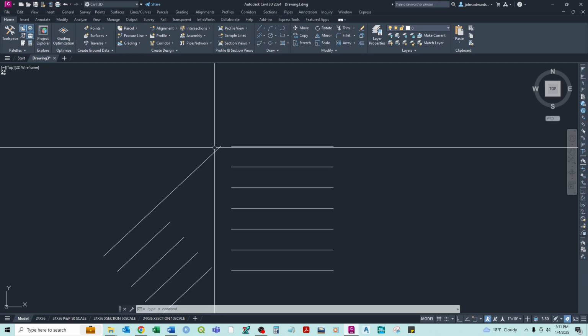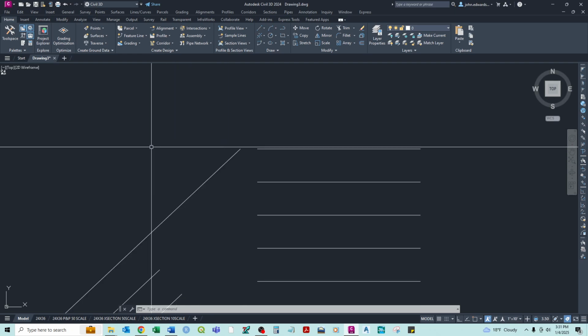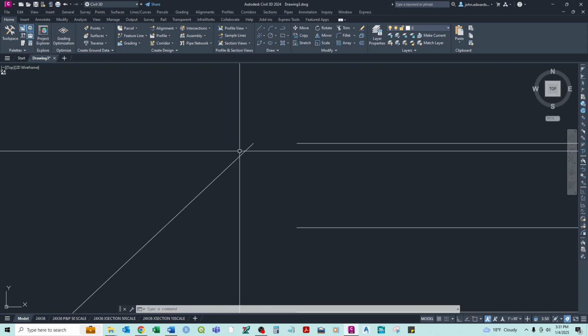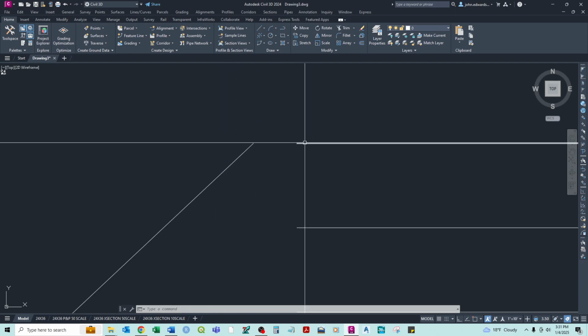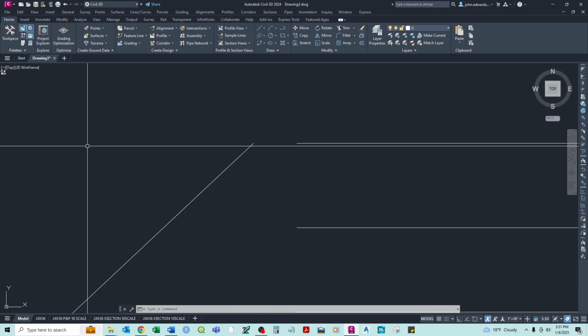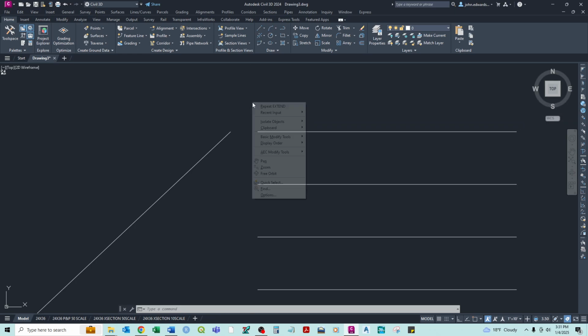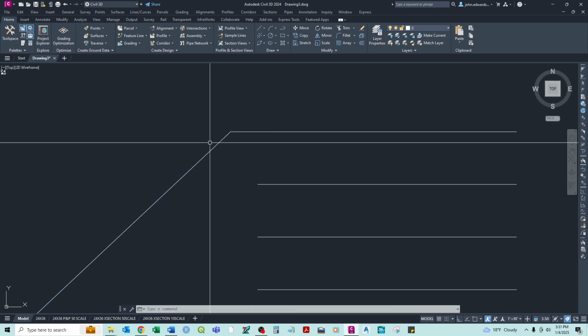Now in old AutoCAD, you wouldn't be able to do that unless this line went all the way across and it could physically touch this line. Nowadays you can extend it to essentially the continuation of this line. But if we wanted these two to touch, we could just do this in reverse, and we extend again where we want to go first, and then the object we want to go there second, and now they can touch.